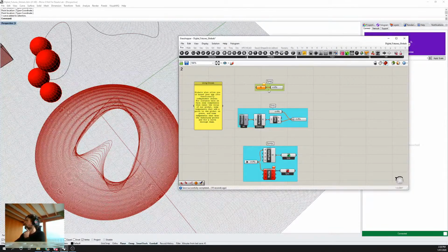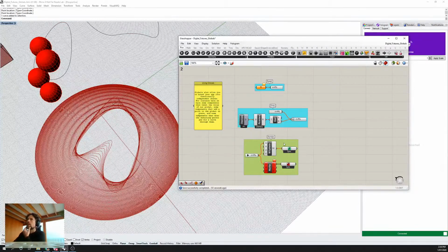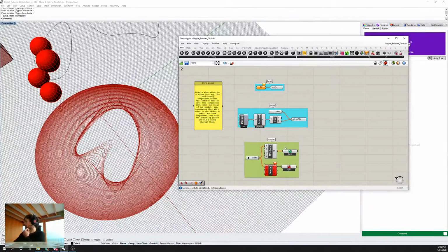It makes building Grasshopper definitions a lot more like how you might build the same functionality if you were scripting or programming. You would be defining functions which are as simple and discrete as possible, and then calling those functions to build up more complex applications. So using global variables to pass data around in your Grasshopper definitions allows you to do things like that. No more spaghetti.